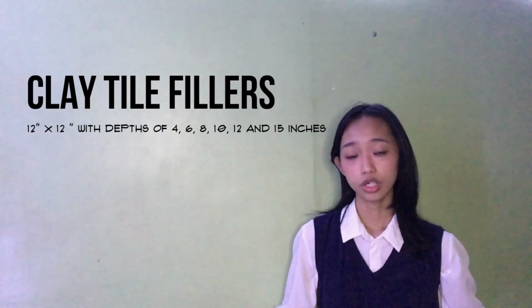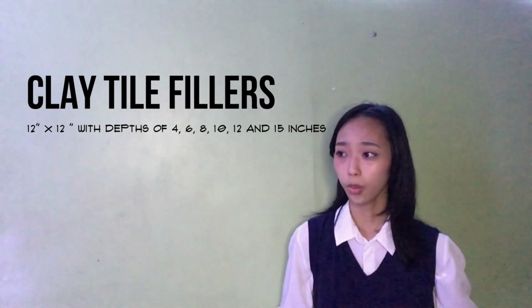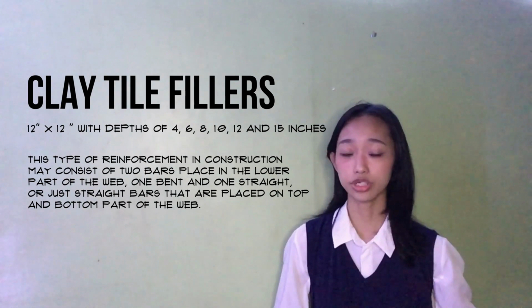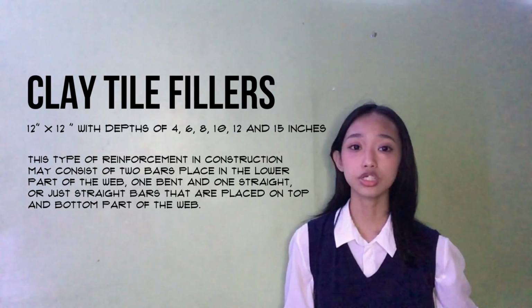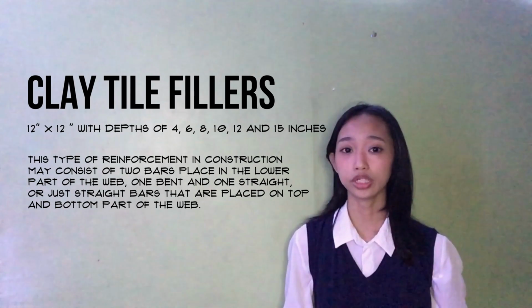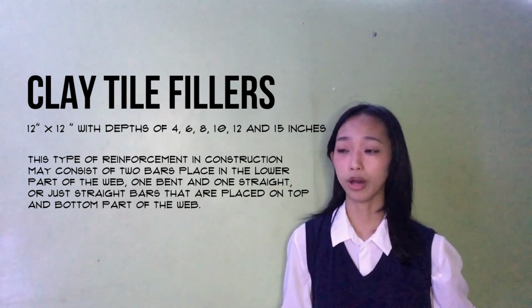Let's talk about the pillars for the slab. The first one is the clay tile pillars. Generally, they are 12 inches by 12 inches with depths of 4, 6, 8, 10, 12, and 15 inches. This type of reinforcement in construction may consist of 2 bars in the lower part of the web, 1 bent and 1 straight, or just straight bars that are placed at the top and bottom part of the web.